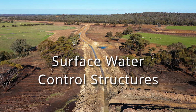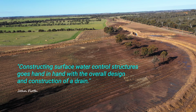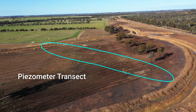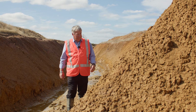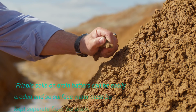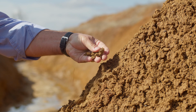Surface and groundwater structures are quite different. If you pull them down to their basic context, surface water earthworks deal with water that flows across the ground. So we're dealing with water that occurs after natural rainfall events. There's a number of reasons why we keep the surface and groundwater separate. First of all, the surface water is fresher. Groundwater drains are generally more saline. We don't want the higher volumes of fresh water flowing into the drains and causing structural failure of drains or erosion or silts or sediments to transfer off-site.